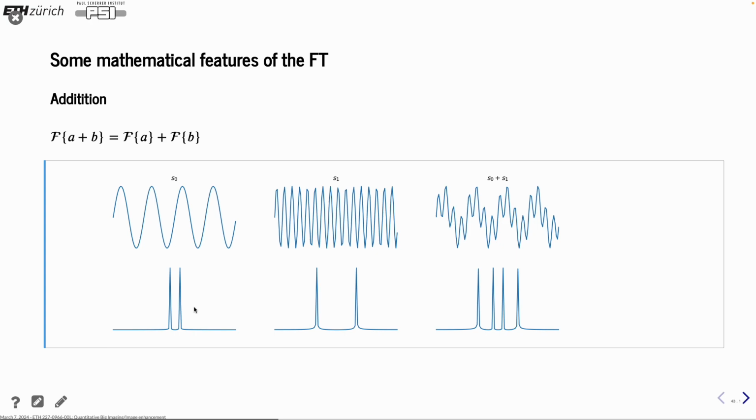And looking in the Fourier space, you can see that this is a low frequency signal and this is a high frequency signal. If you look at the Fourier spectrum here, you can see that of the two peaks that you have, one is for positive frequencies and the other for negative frequencies. So the Fourier transform always shows positive and negative frequencies, and the middle is then the 0. You always get a mirrored effect here. If you have a higher frequency, it goes further away from the 0. And if you do the sum, you can see that it's actually the combination of the two of them like this. If you took the Fourier transform of this one, you would get that too. So this is a very basic demonstration of how frequencies are put together with the Fourier transform.